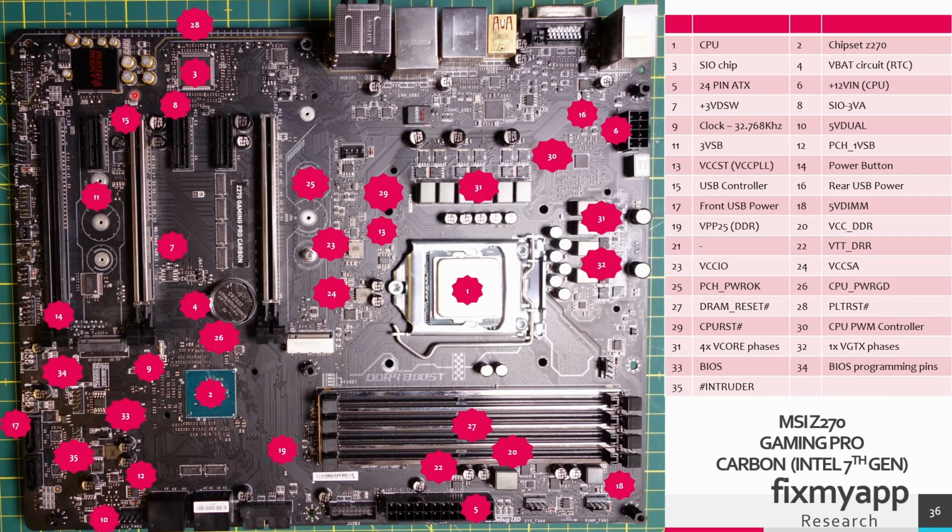This USB power controller will determine what will be the plus 5 volt for the rear USB connectors and the front USB connectors. Depending on the sleep state 3 and 4, it will deliver power to the front and the rear USB ports. And the plus 5 volt voltage can come from the ATX power supply when it's turned on, that is the VCC5, or it can come from the 5 volt standby voltage. If you want the USB ports to be active in the standby mode, if you set this option on in the BIOS settings, this controller will send a signal to generate the plus 5 volt from the 5 volt standby voltage regulator.